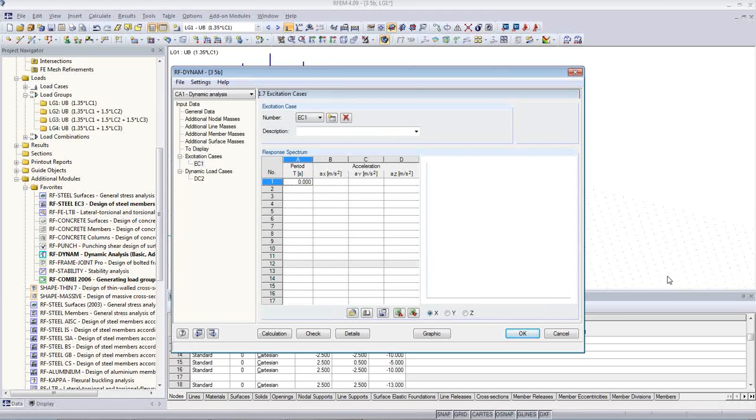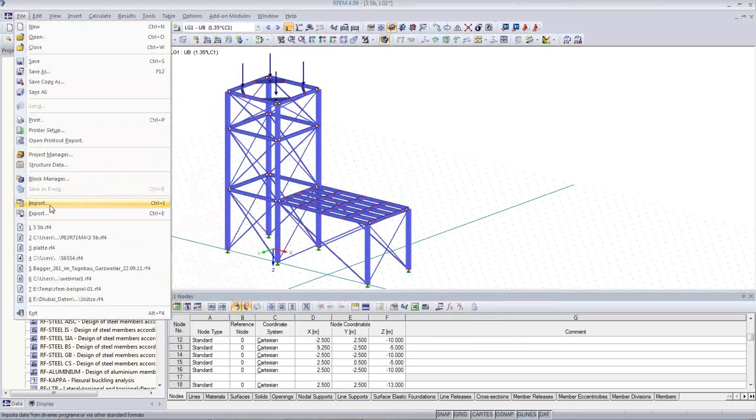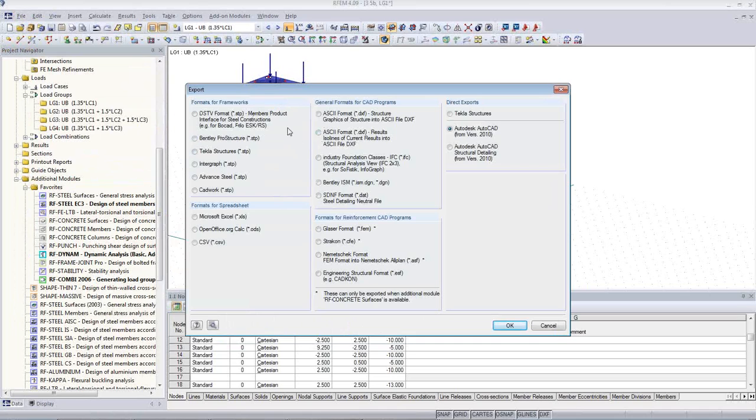Export structures into DWG format. We can export it. There is a lot of things for CAD. We can import and export the structures to different formats: DSTV format, DXF format, IFC format, and the DWG would be basically a new option that we have. We gained it through an interface to the ISM, integrated structural modeling from Bentley, and with this you can export it to a viewer, basically a synchronizer, that you can download for free from the Bentley website, and then you create a DGN file, and with this DGN file you can import this in AutoCAD, and then you have also the real cross-section information in this DWG file.